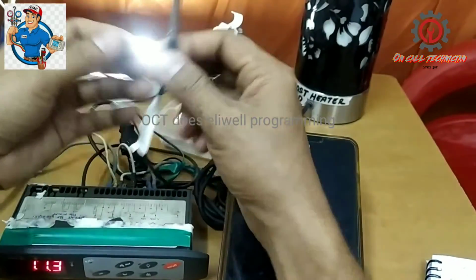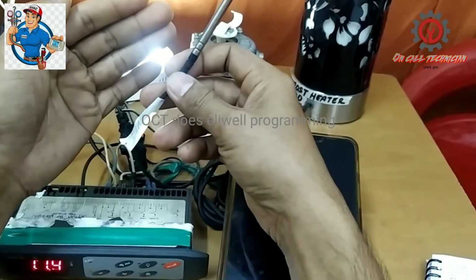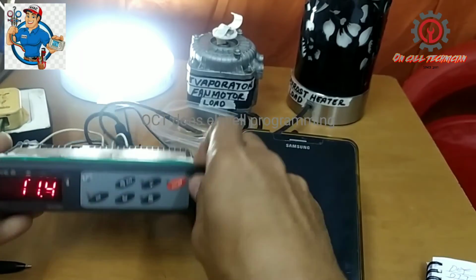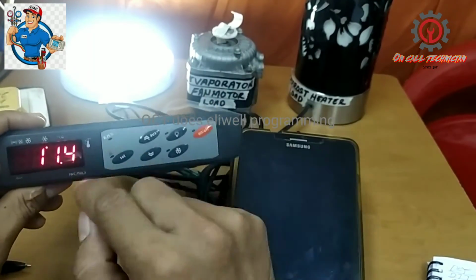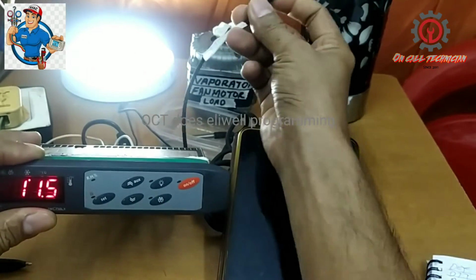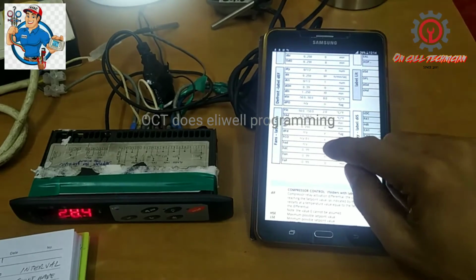So I suggest do not disable this evaporator sensor if you use it. Okay, for example, you want to use it for a chiller mode only, which is the setting I use, a chiller, so do not disengage this one. Let's proceed to the fan folder.